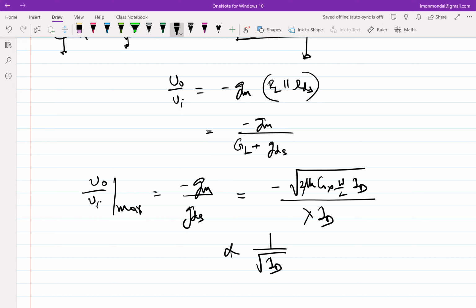So as I said, you increase VDD, you have unlimited availability of increasing VDD. So even then you will not be able to hit infinite gain because it will be limited by GM by GDS of the transistor. You can potentially increase VDD, but you have to accommodate for that. Otherwise, it will go into linear that we saw, right?